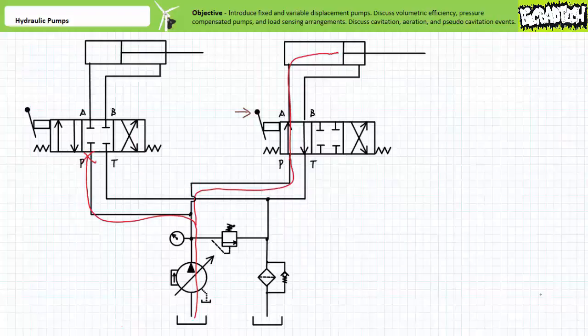The pressure compensated variable displacement pump adjusts displacement to provide flow. When the actuator stalls at the limits of travel, pressure rises to the compensator setting and the pressure compensated variable displacement pump de-strokes to 0 gallons per minute, and the pressure relief valve is not forced to actuate. If leakage occurs while in this position, the pump provides just enough flow to maintain pressure and replace the fluid lost to leakage.